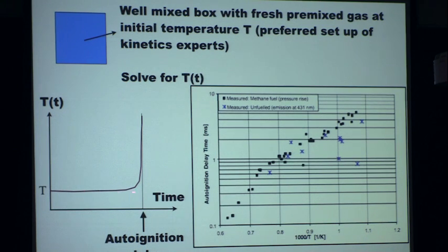They give you what we call the auto-ignition time. If you plot the time here, and the temperature, you see for a long time nothing happens, and then usually, and again that's a specificity of combustion, when it starts burning, you have to start running, because it will happen very fast. And the curves are always like this, and this time is called the auto-ignition delay time, and it can be computed with these tools as a function of temperature. Usually we plot it as a function of 1 over the temperature. And so you see here the temperature is high, the ignition delay is small, and this is the log scale. And here you go to low temperature, the ignition delay grows like the exponential of that.